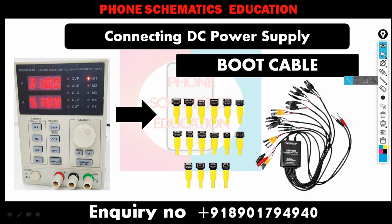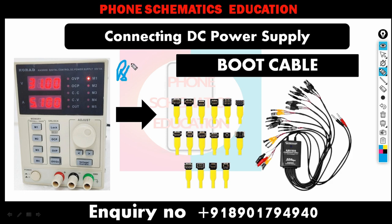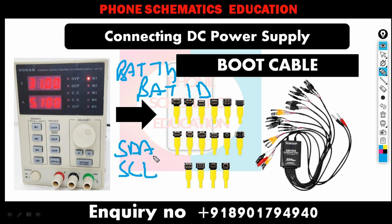Now in the market, you will see this type of boot cable with different connectors attached. Basically, it's a special cable designed for connecting the DC power supply to the phone motherboard. Because in modern phones, there are additional pins in the battery connector called BAT thermal and BAT ID, right? In some phones, SDA and SCL. We are just talking about BAT ID and BAT thermal right now.